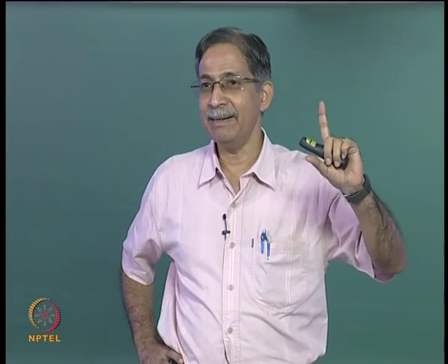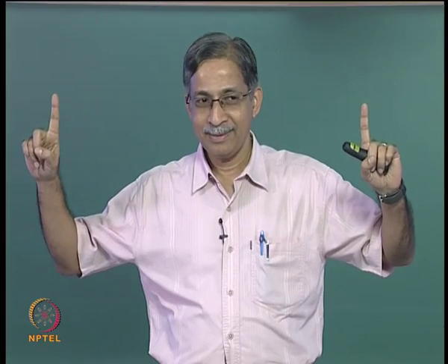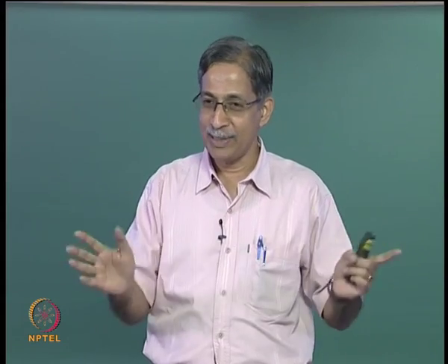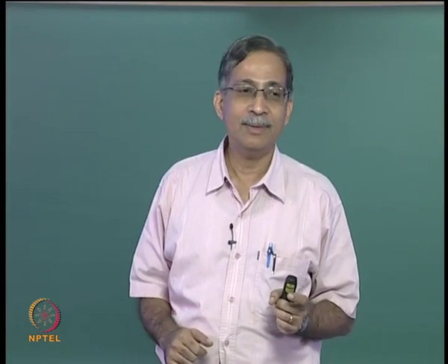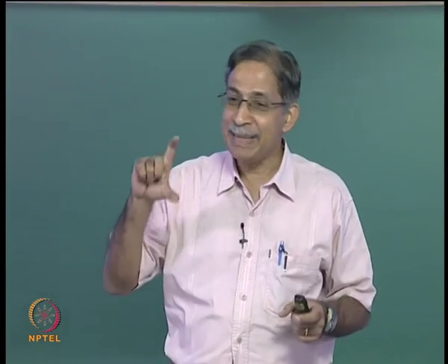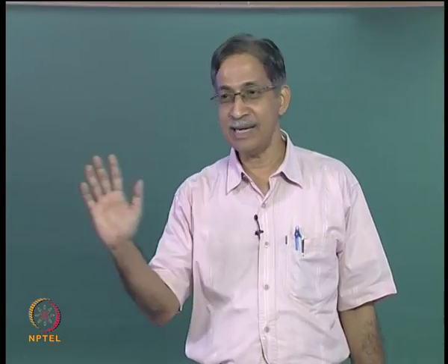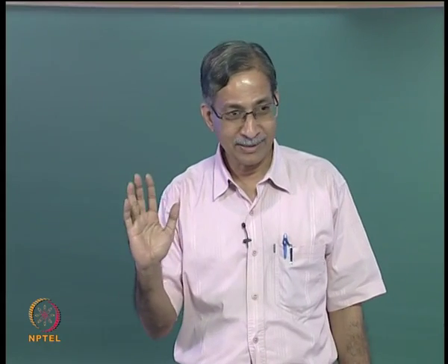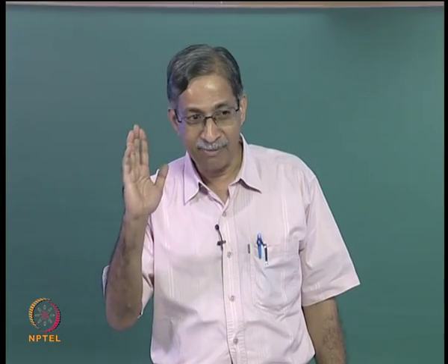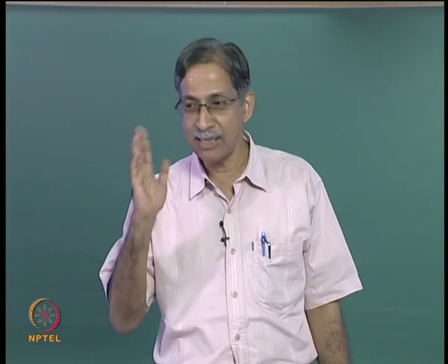Let's be very clear. This is a statically determinate beam. In a statically determinate beam, your midspan moment, will it not always be WL by 4? Whatever you do, plus P delta is what you do in second order analysis, that is what you should say. In first order analysis, the answer will not change. Even if you had material non-linearity, it will not change. WL by 4 remains WL by 4, even if that beam yields, it remains WL by 4.